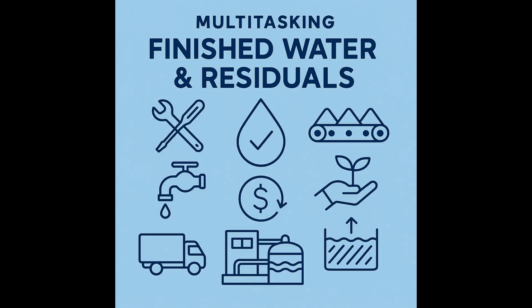Ah, okay. Like what? Well, for instance, polymer management. We mentioned polymers help dewatering. Operators have to optimize the dose, not too much, not too little, for the thickening and dewatering equipment to work efficiently. That takes skill. Right. They're also directly operating the thickening and dewatering equipment itself, running the gravity thickeners, belt presses, centrifuges, whatever the plant has. That's hands-on work. And the permits.